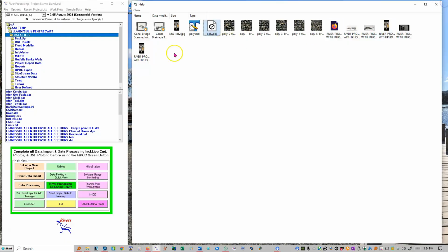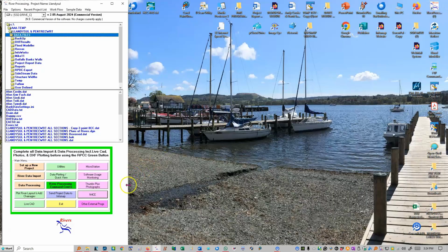So this can be done, and if you wanted to do it, all you're going to do when you come to name your photographs is simply call them CS1-01, and you could call it video or 3D video, whatever you want, because when you come to renumber the photographs, and we'll see that later on, into a chainage suffix format, where the chainage up the watercourse might be 004312 decimal point, and then the cross-section number and so on, it will still work with a video like that.